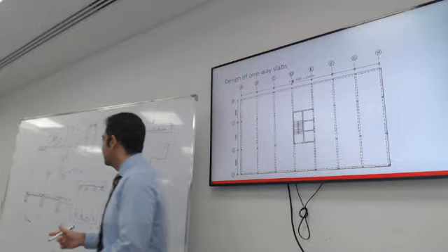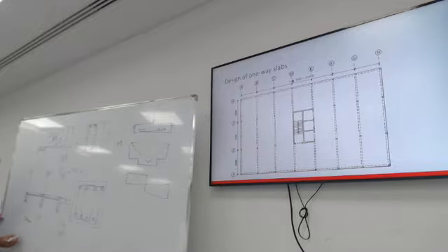Exactly. All right. So can you guess what the bending moment diagram is for this beam if there is a distributed load acting on it? Negative at the support and positive at the midspan and maximum. So where are the supports? What is supporting the slab? The beam.